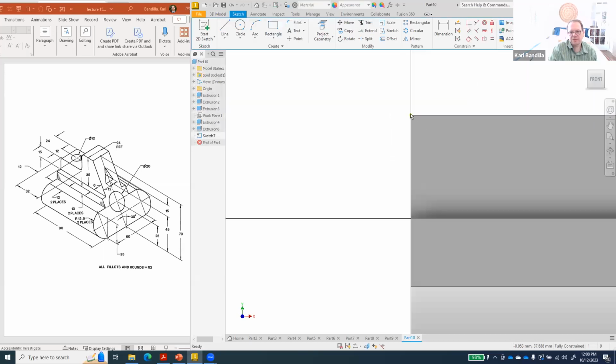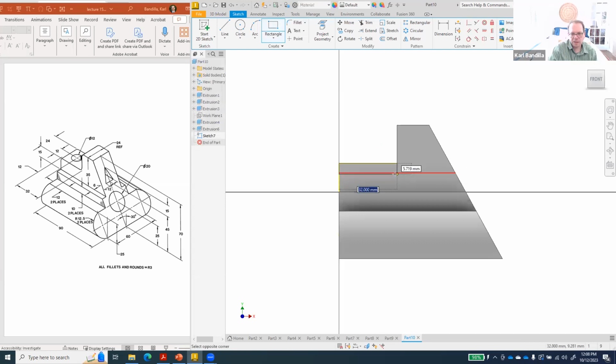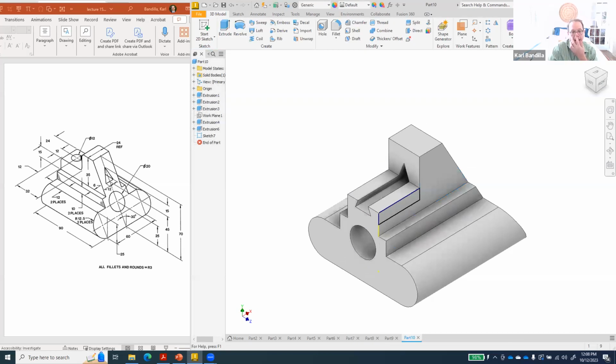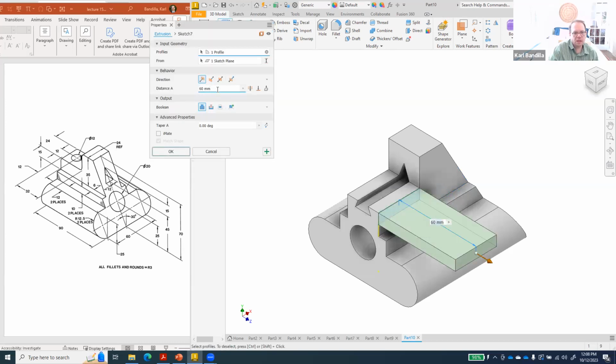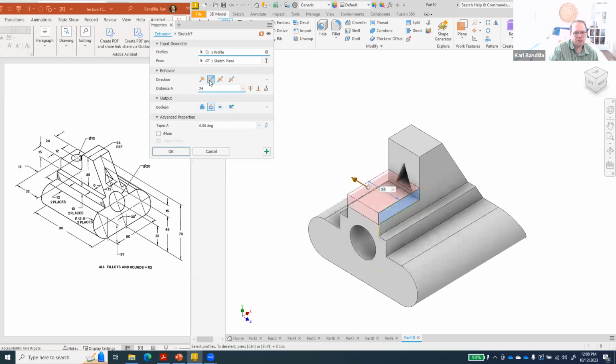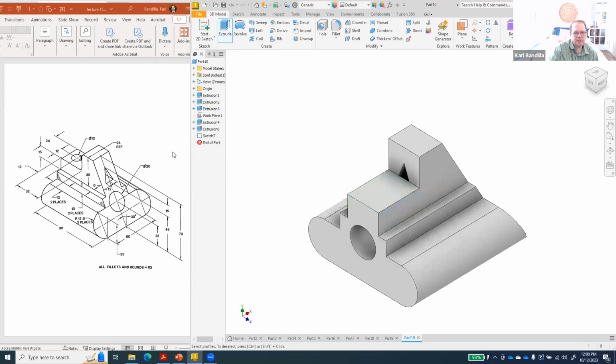Seems to be getting that edge though. It's very interesting. Let's make it double sure. A rectangle here to there. How far down doesn't really matter. And now that was supposed to be 24 across, so we can extrude that. Correction, and now cut. All right, with that, we've closed it off.